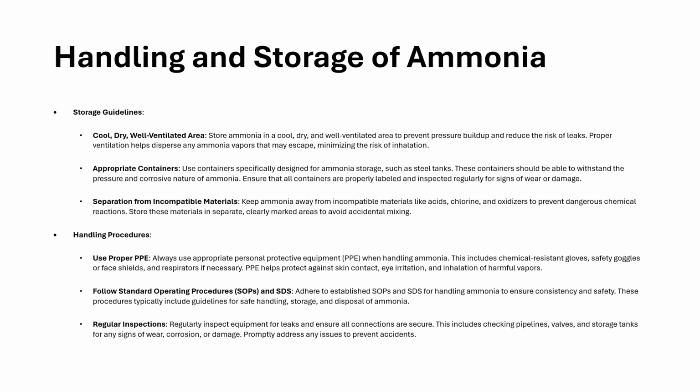Handling procedures. Use proper PPE. Always use appropriate PPE when handling ammonia. This includes chemical-resistant gloves, safety goggles or face shields, and respirators if necessary. PPE helps protect against skin contact, eye irritation, and inhalation of harmful vapors.